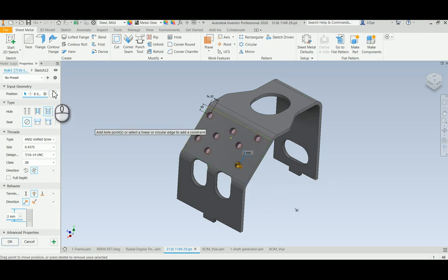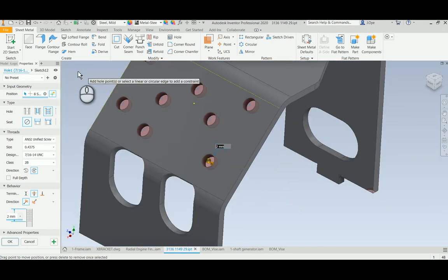Adding to that, if I go to the sketch tab here, I can just rotate it a little bit, and click on this dimension, and I want to add a dimension to that hole. I'll say 28 millimeters. Fully define it here, add this, essentially this vertical value. But actually enter a value.